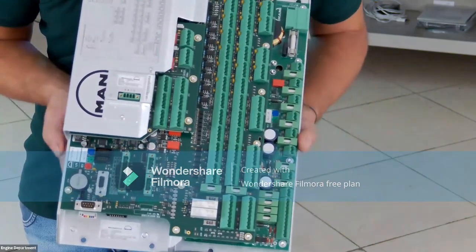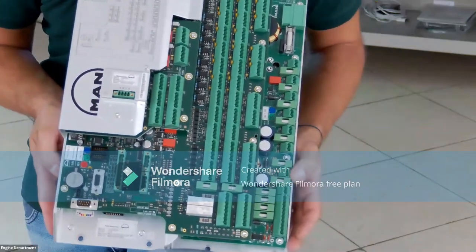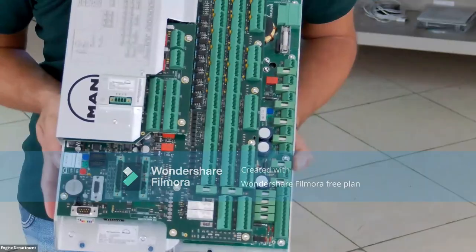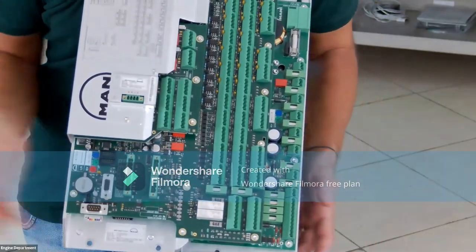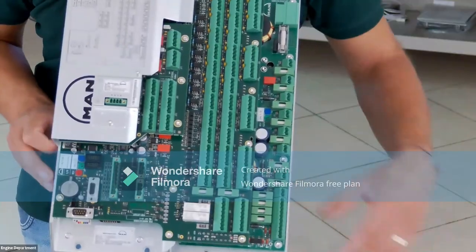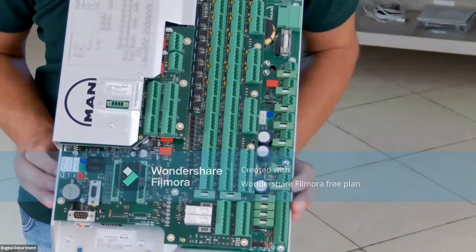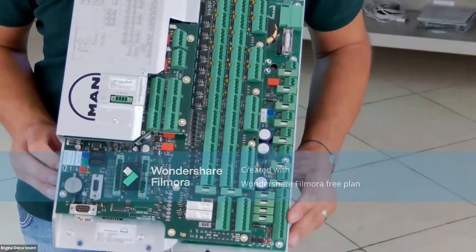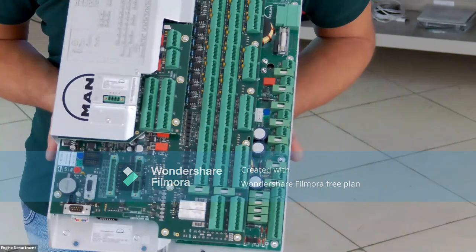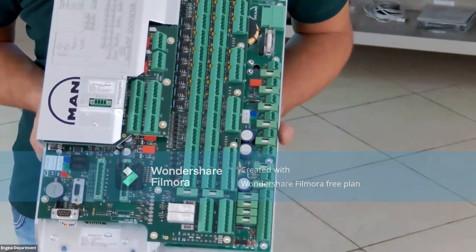But at 80% engine load, maybe the fuel index will be 60%. So if you reset during 60% engine load, automatically the respective faulty MPC, when resetting, will control the respective CCU at the respective engine load. So you will have a sudden 60% fuel injection on the respective unit. So whenever you make a reset while the engine is underway, it is required to perform the reset in slowdown, if you cannot stop the engine.